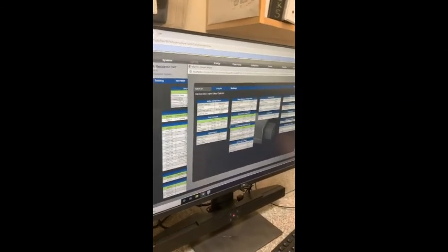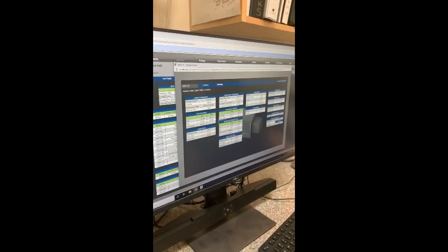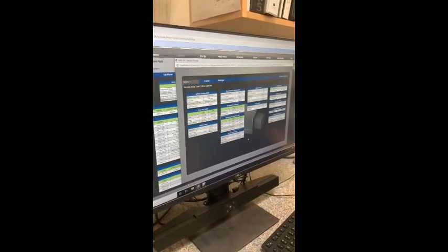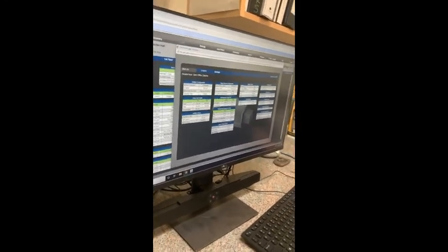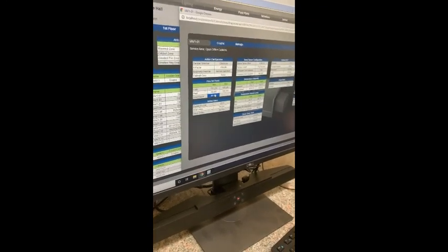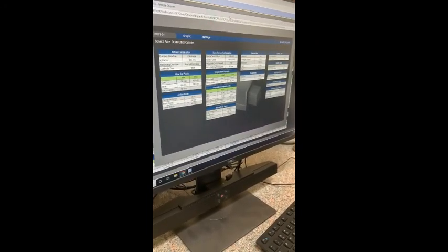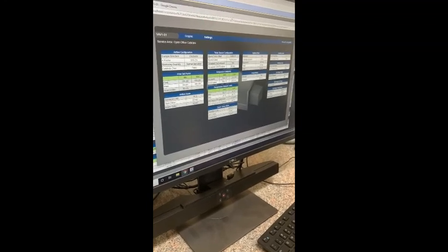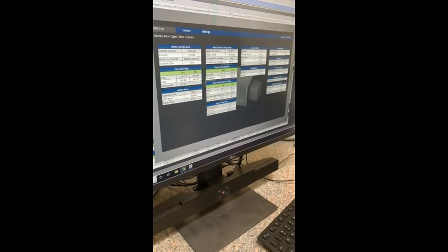And then there's PID loop settings, discharge air temp sensor offsets, discharge temp alarm set points, and whether it's allowed to go into optimal stop. You have your airflow set points here, which are based off your balancing. I can tell you some of these zones seem like they need more air to get the zone up to temperature.